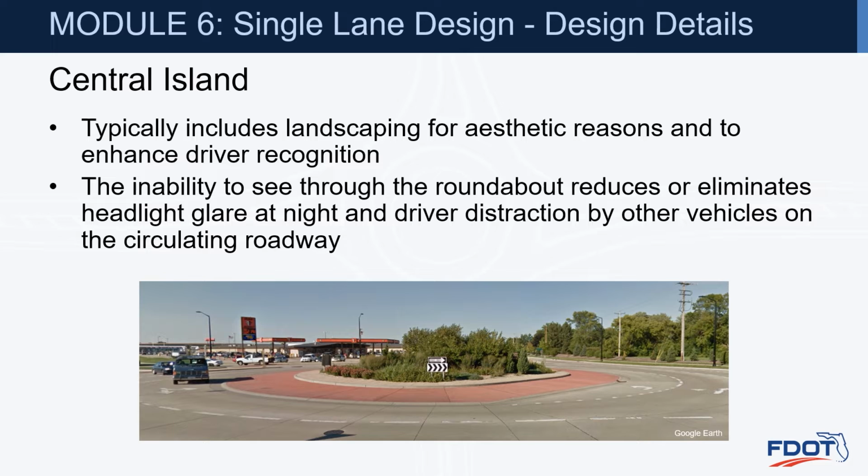Also includes typically landscaping for aesthetic reasons and to enhance driver recognition of the center island. And the inability to see through the roundabout reduces or eliminates headlight glare at night and driver distraction by other vehicles on the circulatory roadway.